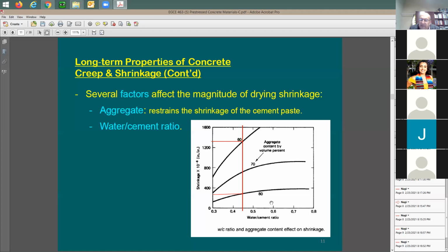Generally speaking, any shrinkage is going to be based on the size of the structural member, of the concrete member. So if you have, let's say, a block or a cube, 12 by 12 by 12, look at the amount of shrinkage that happened in there. Now compare it with 2 feet by 2 feet by 2 feet, like 24 inch by 24 inch by 24 inch. Same aggregate distribution or grading, and same percentage of the aggregate. You're going to see that the 24 by 24 is going to gain more shrinkage, right? So it depends on the mass of the cement that you have in there.